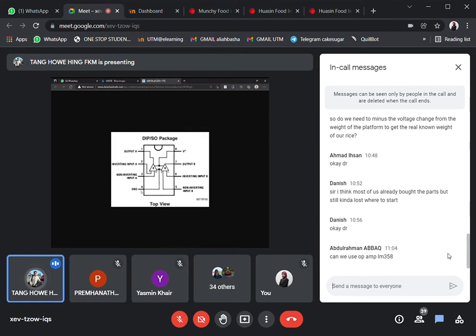So that is the main issue with this LM358, that it is actually expecting a single supply. Okay, it's a single supply op-amp. The wiring will be different from what I have told you previously, using 2 batteries in order to get that. So I won't recommend you using LM358 because it's single supply.